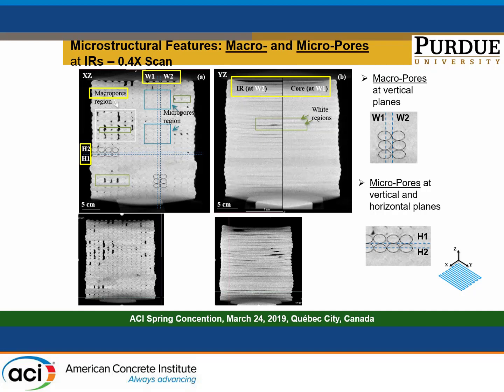There's one that is definitely related to the interface, both in the horizontal and vertical directions, but there's also another series of imperfections in the plane that goes through the cores of the individual filaments, depending on how big the filament is that you are trying to extrude and what the rheological properties of that are.